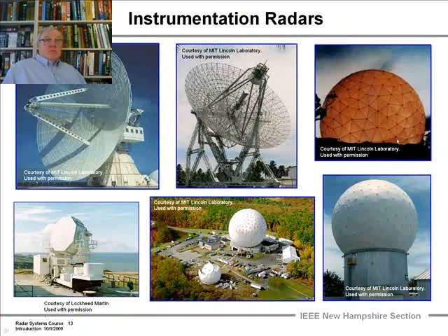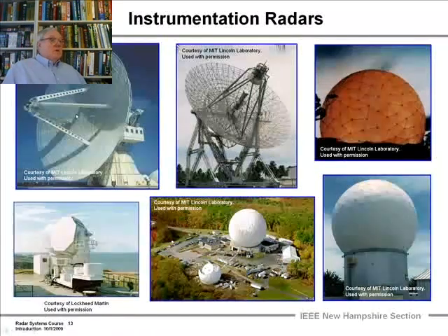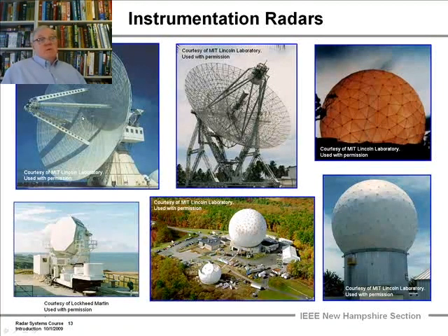This radar inside this radome operates at 5 centimeters, and this is TRADEX, which operates at S-band and L-band, 10 centimeters and 23 centimeters. This one here is so big, I think it's 120 feet across, and when it rotates in azimuth, there's a set of railroad tracks down here. I'll show you later a picture of a man up on a little gallery next to this antenna, to give you an idea of its size in the antenna lecture. These are big instrumentation radars.